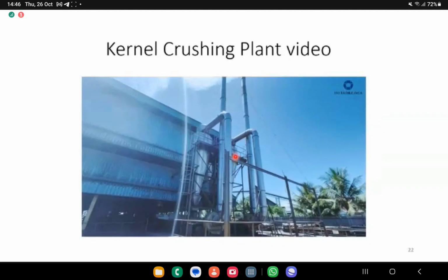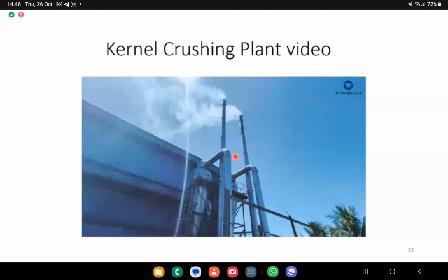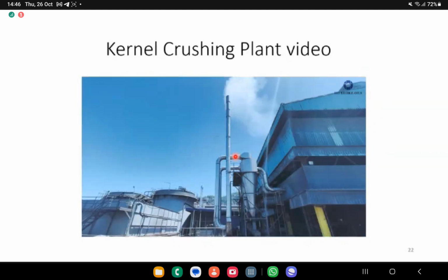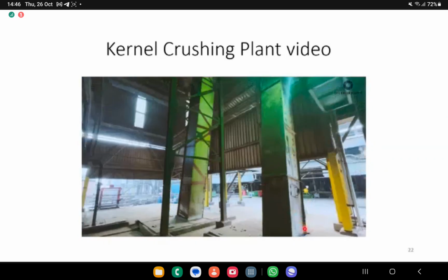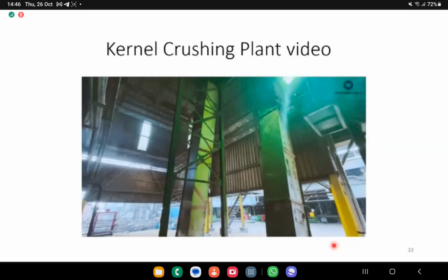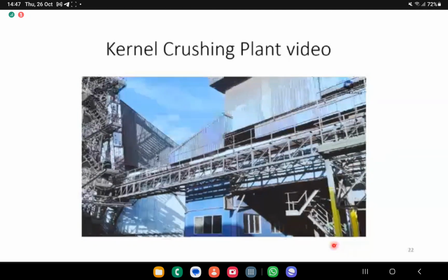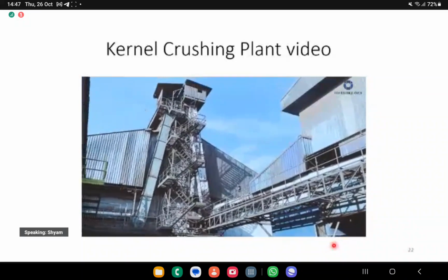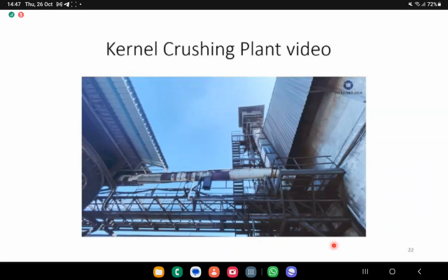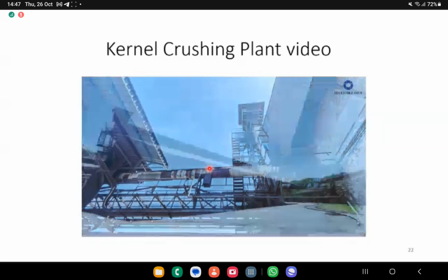Meanwhile, a dust collecting system is installed to recover finer PKE back to second pressing station, besides providing good working condition in the plant. On the other hand, solid output from palm kernel expeller (PKE) is transferred to metal magnetic screening. PKE oil content and moisture will be controlled ideally. PKE that is sent to warehouse will go through extra quality assurance with magnetic screening. Soon it will be exported as animal feed.